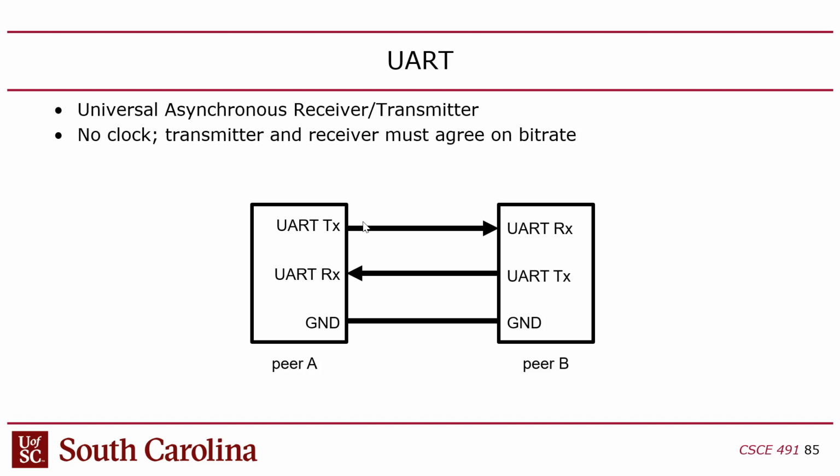Because I'm going to switch topics now and talk about UART. You guys might have heard of UART. It stands for Universal Asynchronous Receiver Transmitter. This is the protocol that's used for text, usually terminals. This is also a serial protocol. 1 bit at a time is sent through the channel. And like SPI, it's bidirectional. So there's a bit flowing in both directions, 2 data bits in opposite directions, right?